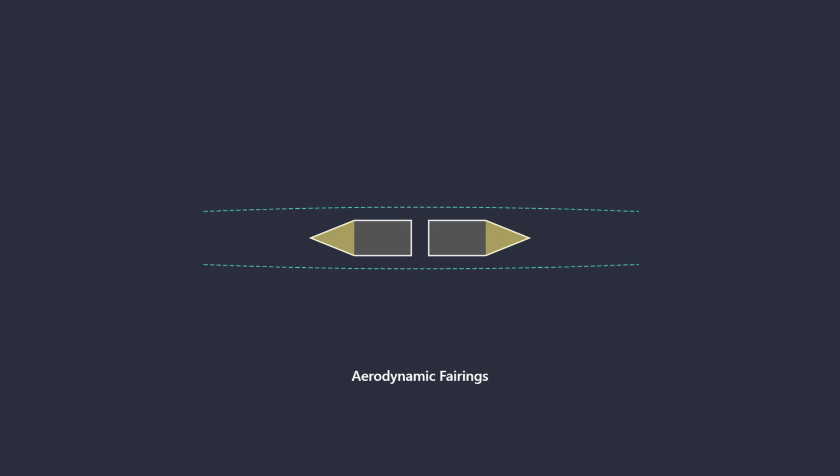Fairings are aerodynamic extensions attached to the deck edges that smooth the airflow transition. Fairings effectively increase the critical wind speed required to initiate destructive flutter, providing an essential safety margin. These geometric modifications are fundamental for achieving inherent structural stability against dynamic wind loads.